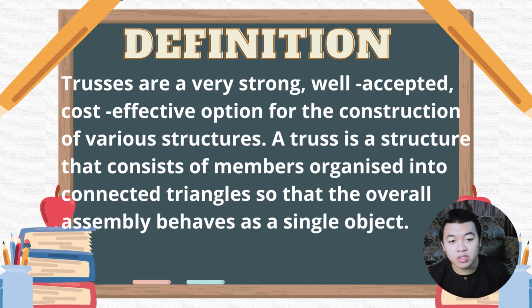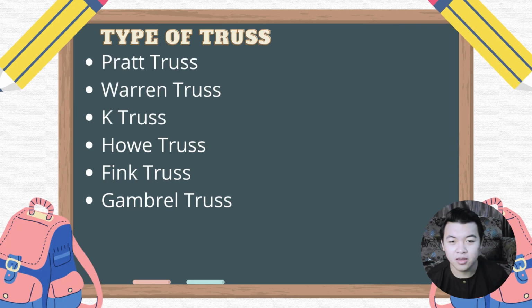The external force applied to the system and the direction at the support are generally applied at the nodes. When all the members are applied force in the same plane, the system is a plane or 2D truss. The principal force in each element in a truss is axial tension or compression.